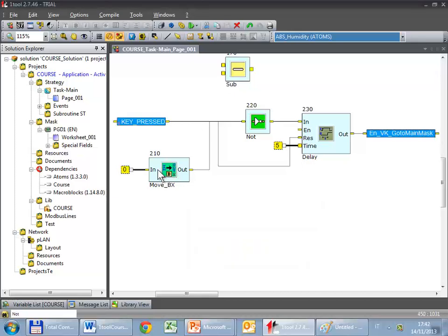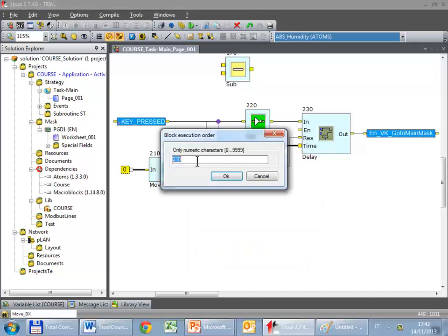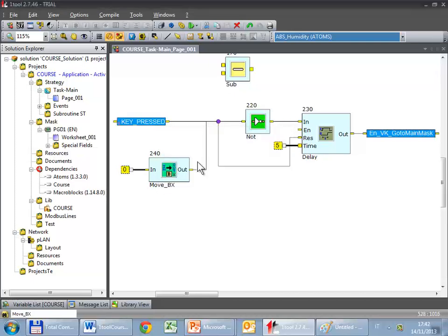Something like, okay, double click 240, for example. So if you press a key, this variable becomes 1, this one writes 0 in the output, this block triggers the internal trigger, and after this block resets the variable. So after, not before.